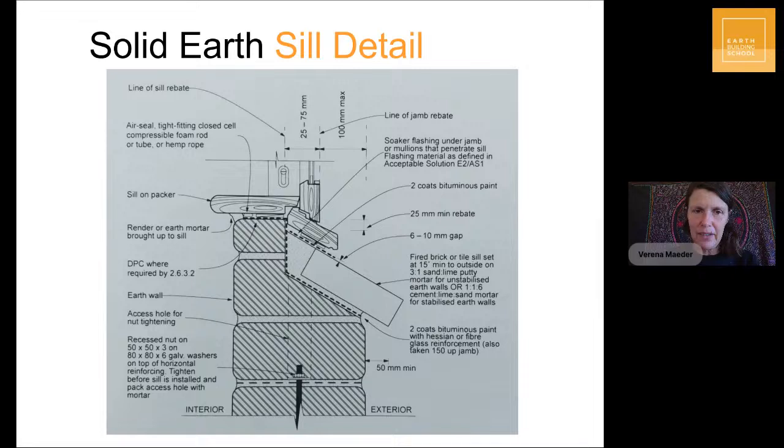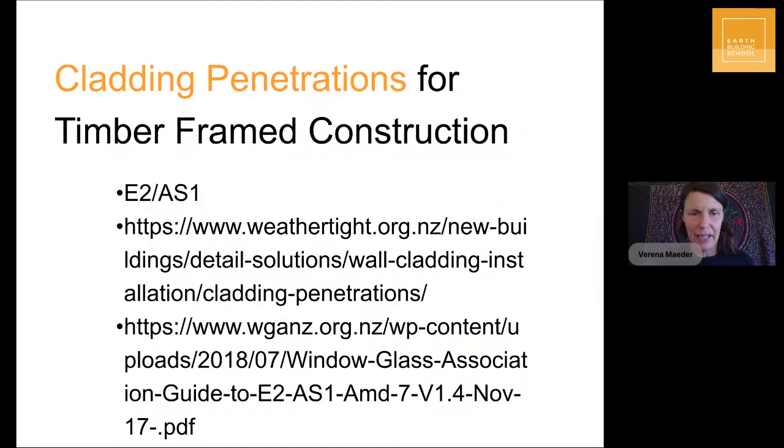And this is typically something that I see happen: people set up the windowsill, but then they later plaster, and then the windowsill doesn't stick out enough anymore. So when you're building, think about whether or not you want to plaster and really install a windowsill that has this minimum 50 millimeter overhang, which ensures that the water actually drips off. And you have enough fall, and the windowsill is made of a material that can handle the water and so forth.